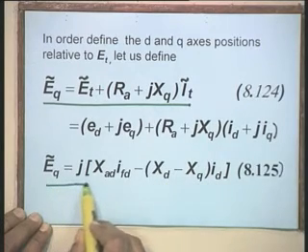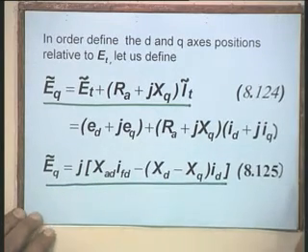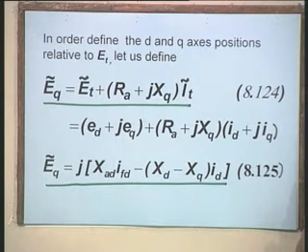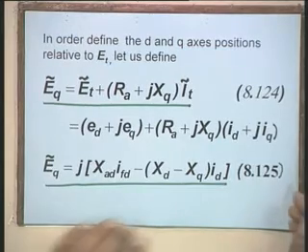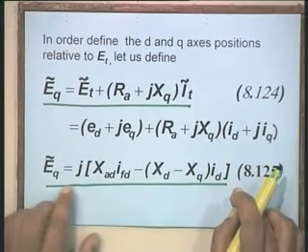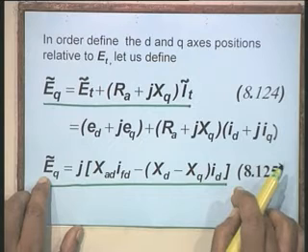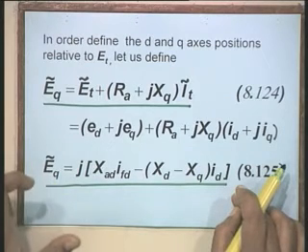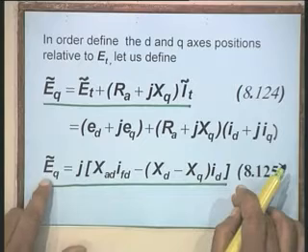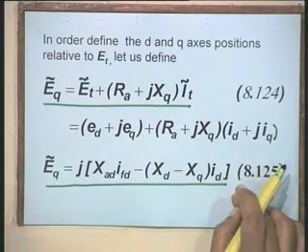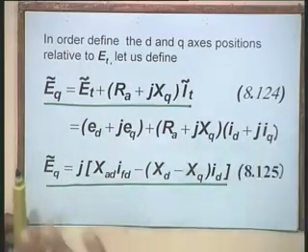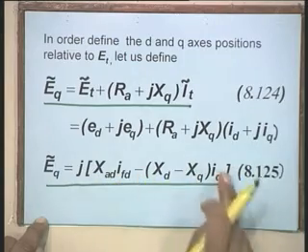What does this equation convey to us? This equation conveys that this voltage EQ which I have assumed is in quadrature with the d axis, that is, it is along the q axis, because with reference to the reference, this quantity is ahead by 90 degrees, that is, the j term is existing, because the other terms are all scalars. Here actually the terms are all scalars.